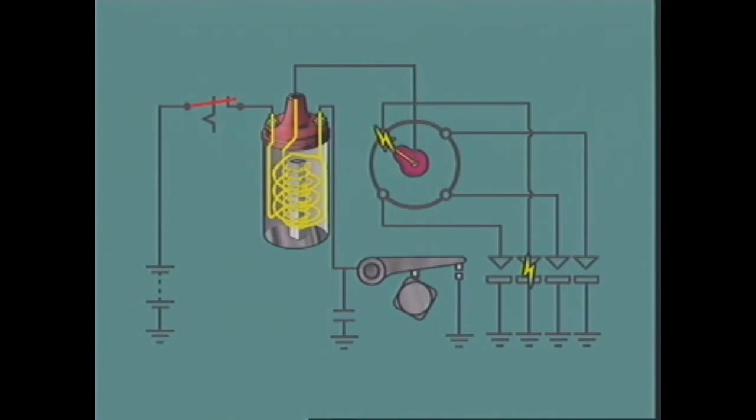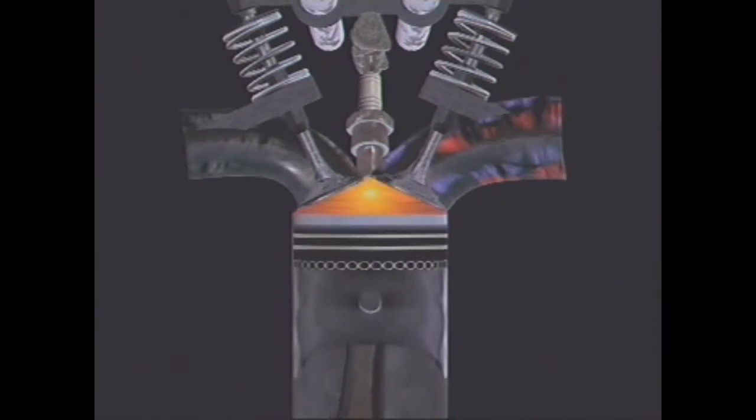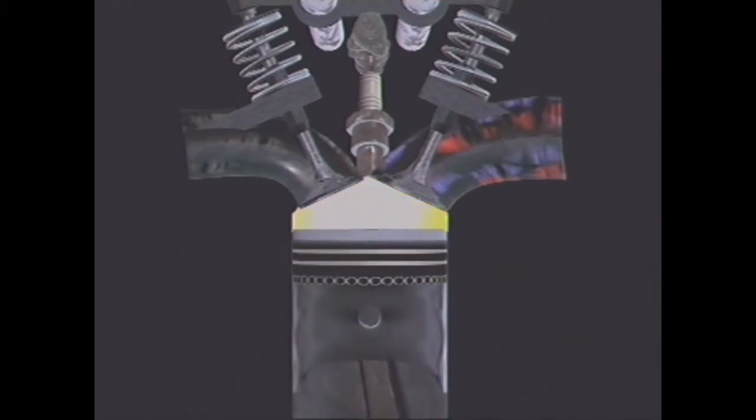As soon as the secondary voltage reaches a value where it bridges the gap across the spark plug, the voltage in the primary circuit falls to a value below that of the charged capacitor. The capacitor then discharges back through the primary circuit, causing further induction, a continuation of the spark at the spark plug, and another charging of the capacitor. Current continues to oscillate in the primary circuit until all the energy in the system is exhausted. This will maintain the spark at the spark plug for about 2 to 3 degrees of crankshaft rotation.